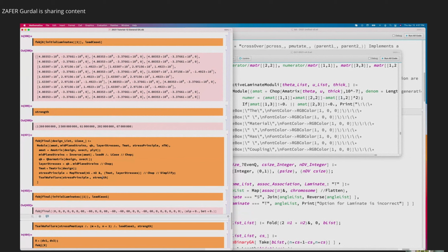So let me stop here, and I'm going to send you this so that the Tsai-Wus are now computed. This last objective final should complete that, and you'll get the working version. I don't see why it's not doing it right now, but it's some simple thing that is not a big deal. But it will basically compute the Tsai-Wu numbers. So with this, you're going to be able to compute the Tsai-Wu number as an objective function. And if you want to minimize or maximize this Tsai-Wu failure number, this will be what is going to be used.